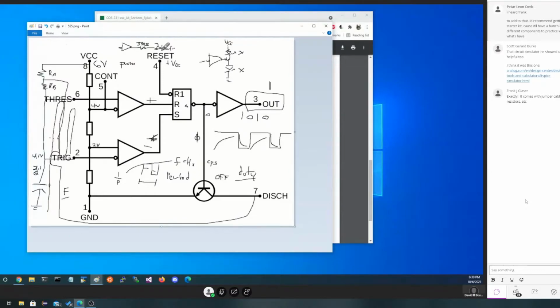The body doesn't respond to things linearly. Same thing happens in the case of the brightness. It's not exactly as exaggerated, but we're going to perceive a 50% increase or decrease in the brightness. You could go either way. We're going to perceive a 50% decrease with a 25% change in the duty cycle. So instead of, let's say, 100%, we're going to bring it down to 25. The person is going to think it's only dimmed the light by half, even though we caused our number to go down by 4. So we will do some work with pulse width modulation toward the end of the semester.